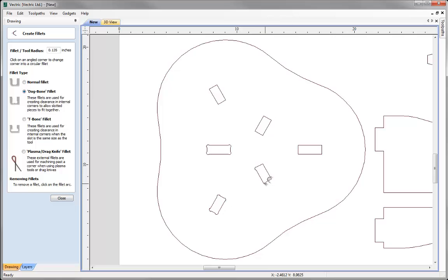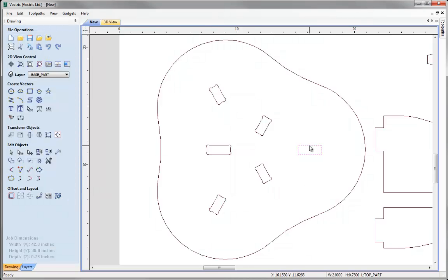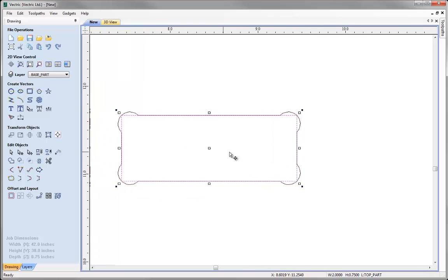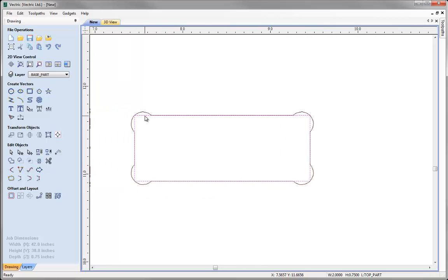So I'm just going to go ahead and add the rest of these. And what I'm going to actually do to demonstrate to you that this will actually work is I am going to close this. I'm just going to copy this square here. I'm just going to turn that into transform mode first, and then I'm going to just drag that over here, and you'll notice that now we've overcut into the corners. If you imagine that this rectangle is our tenon, now we've overcut into each of these corners, our tenon will fit into this multi-slot perfectly.